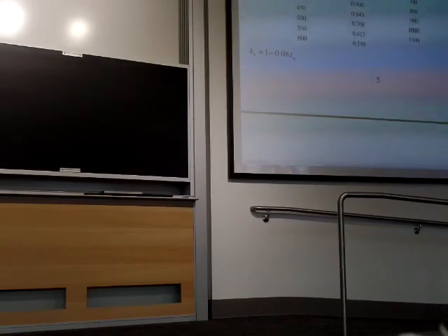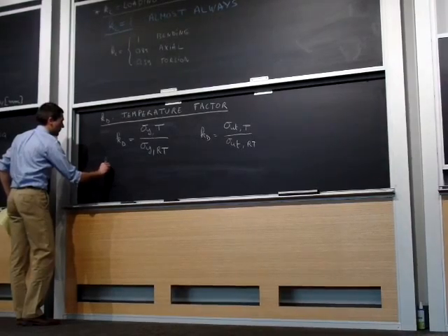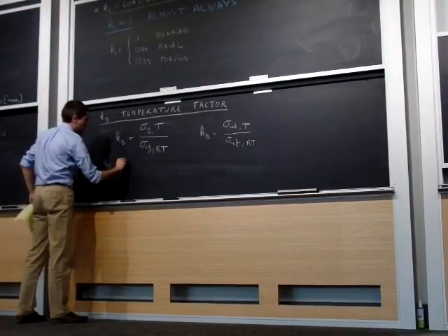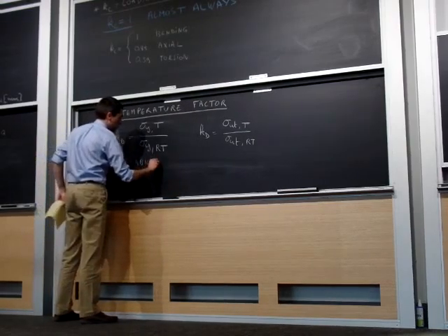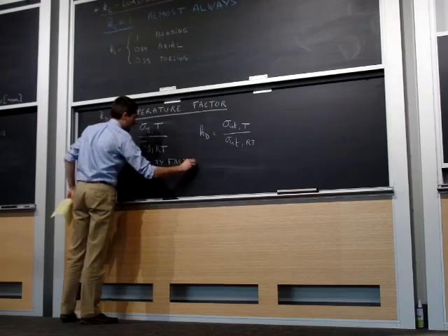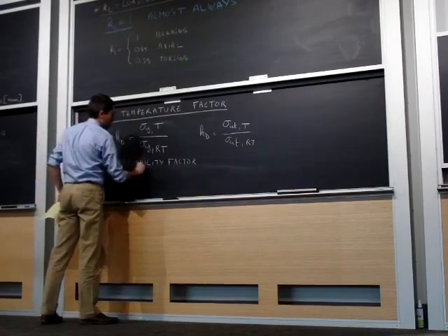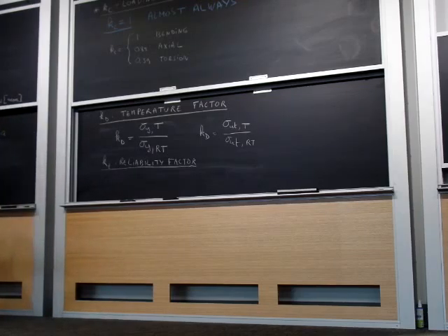All right, we got 2 more parameters to go here. The one to last one is Ke, which is the reliability factor. Intuitively, if you want to have increased reliability, would you over-design or under-design?